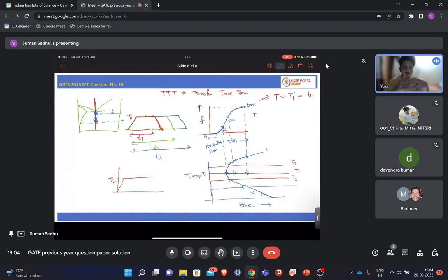So you will get one optimum temperature where the nucleation and growth rate combined will be maximum. So let's say this point is this one. As you go above this point, your nucleation rate will decrease, but growth will increase, and overall it will decrease. And that's why the time required for the same percentage of transformation will be higher.